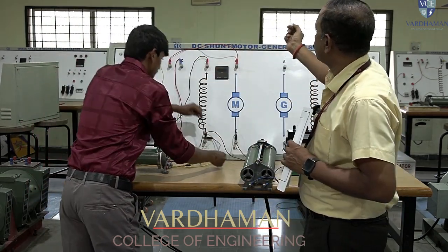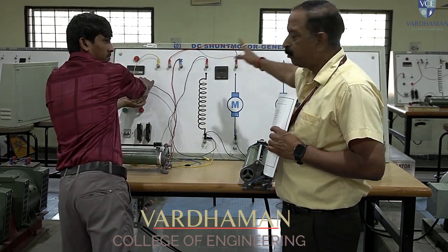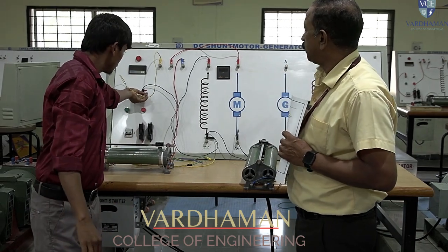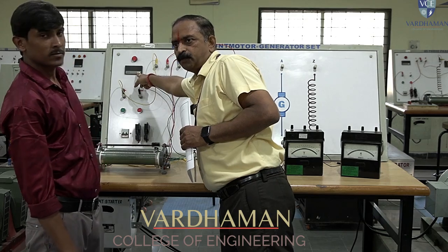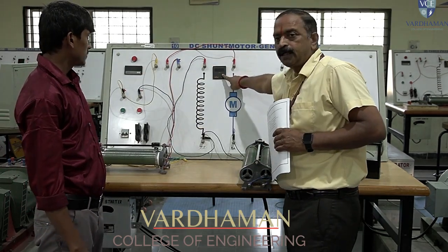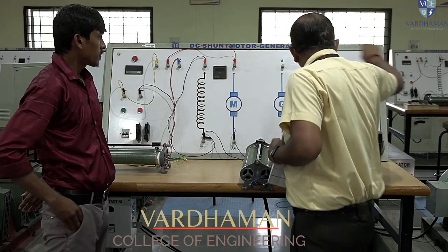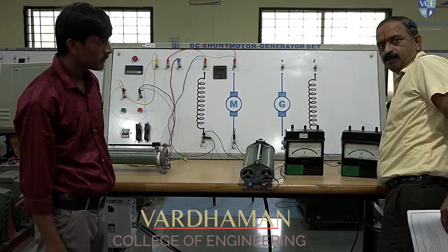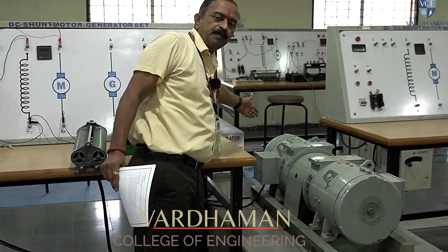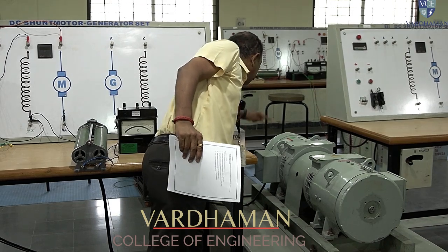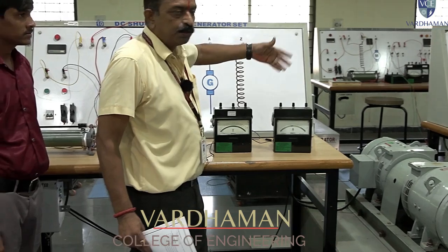We have not connected any meter in the motor section because our experiment is connected to the generator. All the meters are connected at the generator. Anyhow, we have a display for the voltmeter here. We can get the display of the voltage here, and this is internally connected. This reads the speed of the motor in revolutions per minute. The speed of the motor is sensed by a proximity switch at the backside of the motor, which you cannot see. The proximity switch senses the rotations and displays in this meter the speed at which it is rotating.